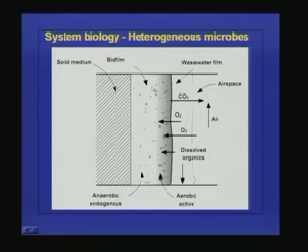So this film will be in anaerobic conditions, and if the thickness of this film increases further, what will happen? The dissolved organic penetration will also be limited. The microorganisms here will be utilizing a portion of the organic matter, and the concentration of the organic matter will be reducing with respect to the distance. So microorganisms here may not be getting enough food. As a result, they will be undergoing endogenous respiration, and once the complete endogenous respiration of the layer here takes place, the entire biofilm will be peeling off from the supporting medium, that is known as sloughing.